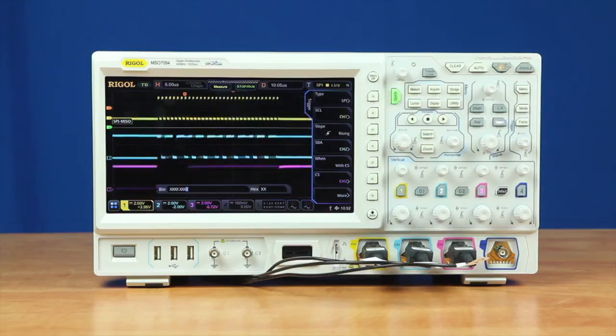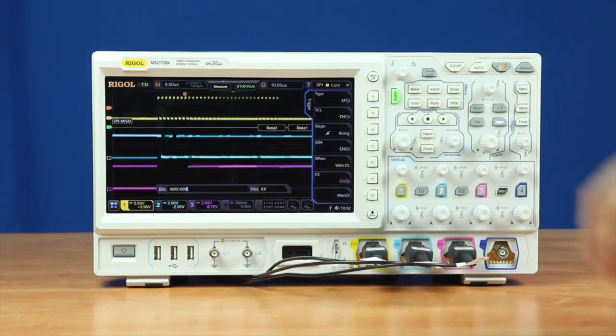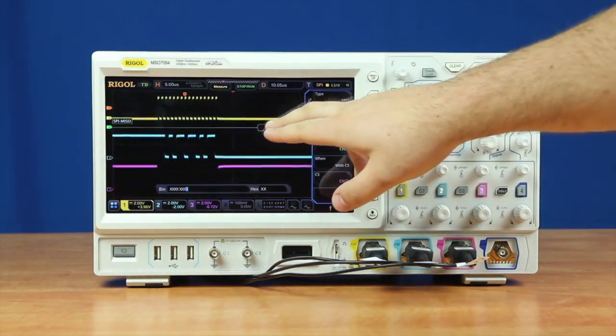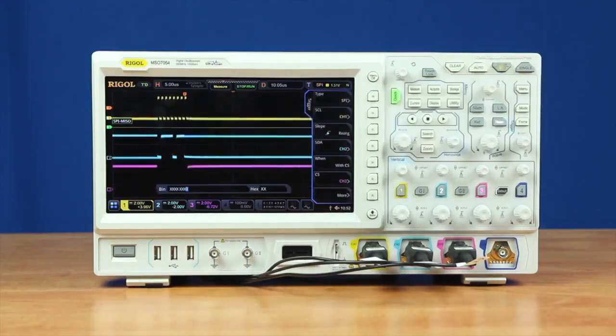The key to any low-speed serial application is the ability to quickly and easily look at the data being transmitted. Ideally, the best means to do this is by having a decoded signal that you're viewing on your embedded device. To start off with, I've already set up the scope to be triggering on and then decoding a pretty basic SPI signal. And we've got our trigger menu on the right-hand side of the screen, and then we've also got our decode bus in green here.